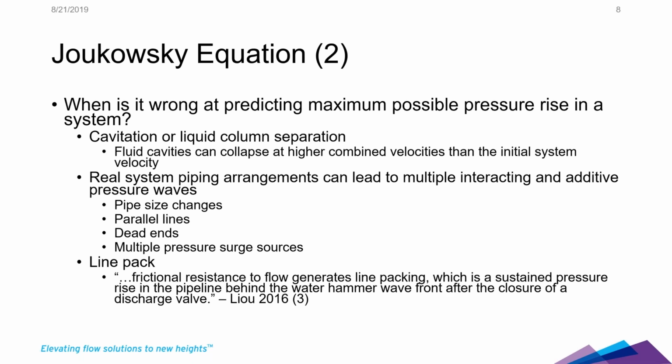You have to put that into Impulse, but you can look at the graph values of velocity upstream and velocity downstream at a node where cavitation is forming, and right when it collapses, that velocity change is going to correspond pretty dang well with the Joukowsky equation.